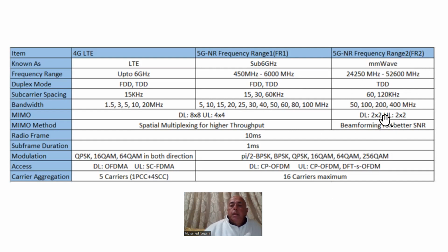Okay, and of course, the signal generation is really not just plain quadrature amplitude modulation. It's really an OFDM signal. So meaning the signal is orthogonal multi-carriers that are modulated, that contains preambles, midambles, and pilot channels and pilot symbols. So it's a very complex signal.